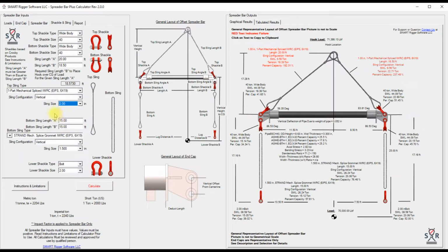So there we go. Could probably go with a quarter, maybe a little lower. Not quite there on the heavy side of this. And there we go. So we run through the calculation to update it for the top slings, get the capacities where we need to be.